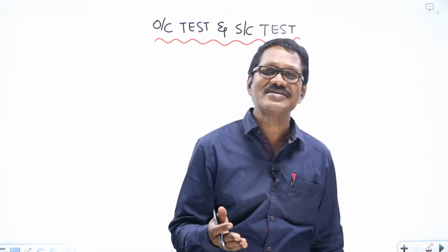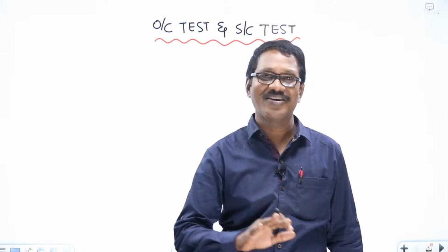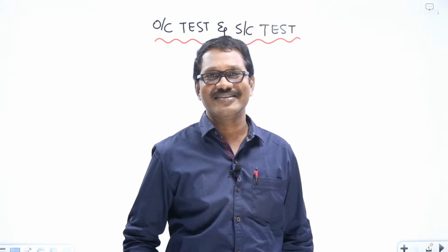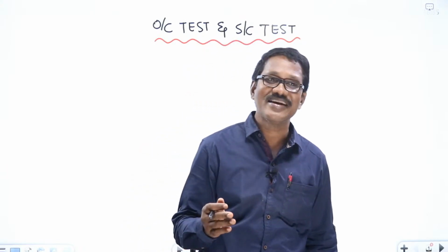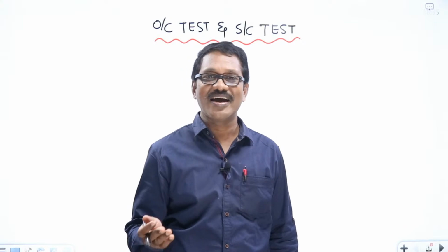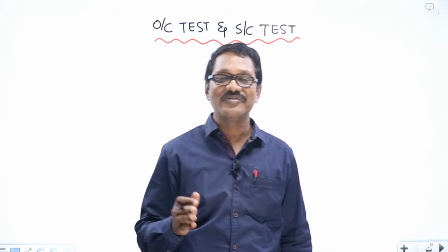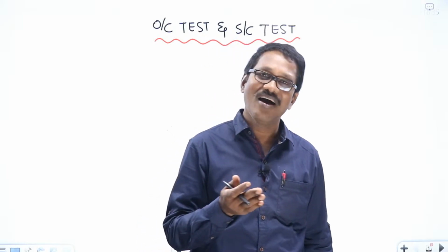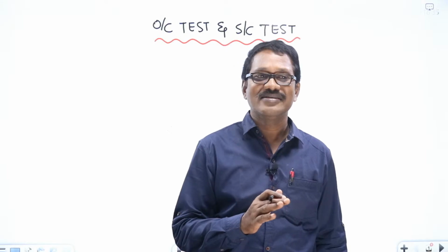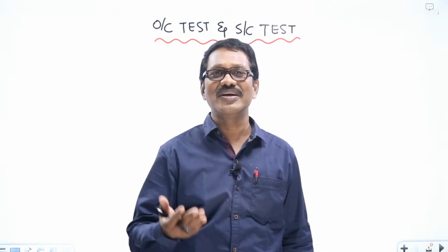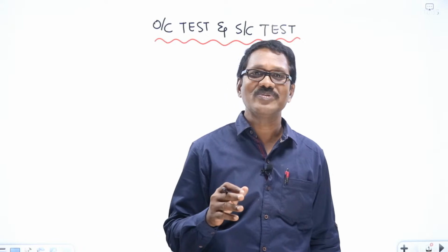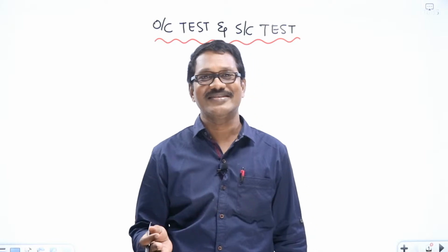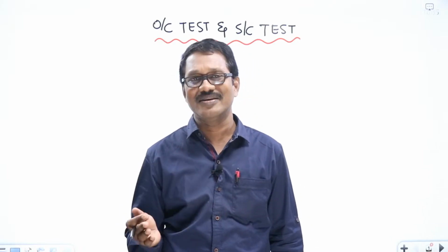Basically, a diode is a true electronic switch that toggles between two states, on state and off state. When current conduction takes place, it is said to be in on state. If current conduction does not take place, that means the external voltage is insufficient to cancel the barrier, then the diode is in off state. Once it is in on state, it performs the task assigned to it. What is that task? Rectification, which converts AC to DC, broadly speaking.